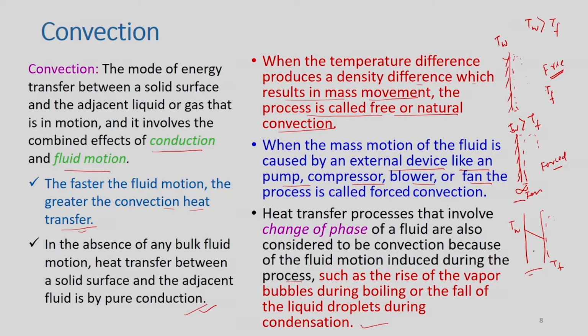So, what I have drawn here, this is the wall, and in the immediate vicinity of this wall there will be a fluid layer. This is the fluid layer. So, before convective heat transfer takes place, there is a very thin layer that exists when the temperature of the wall is more than Tf. So, here pure conduction will take place, and then only convective heat transfer will exist.